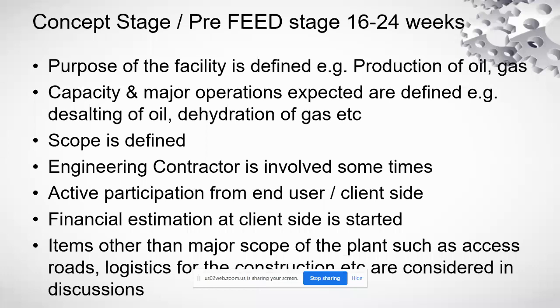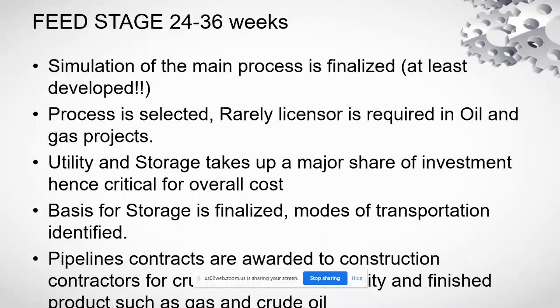After this pre-feed stage, the project enters the feed stage. This is mostly 24 to 36 weeks, again depending on size. Simulation is started in the pre-feed stage, and we can say a skeleton of the simulation is completed there. In the feed stage, the simulation of the main process is finalized, or at least developed,